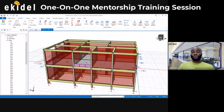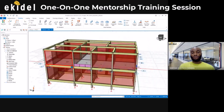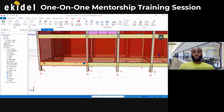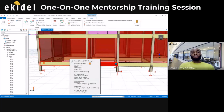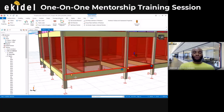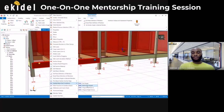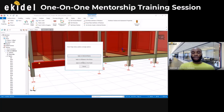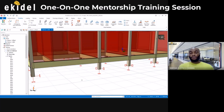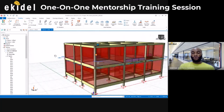Yeah, you can choose to also apply hinge to these ones that you did here, or just leave it to this one here. That's hinging level and all that. This is the same way we used to hinge. Now, let me say I want to hinge this end now. I'll click on this beam now, which is the J end. Right click now, the same thing, say hinge. Apply hinge at J, not that, just say yes, it will be there too. But let me just cancel, not that. Okay, so with this now, we have done the modeling for this beam.